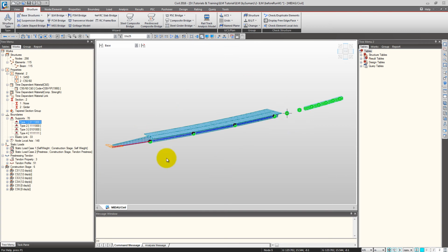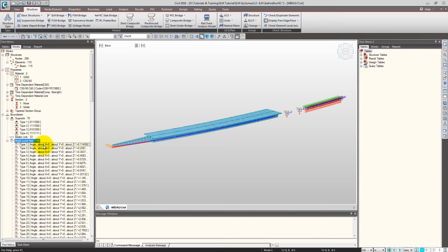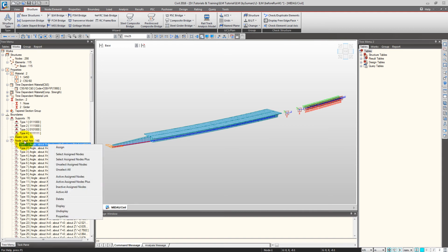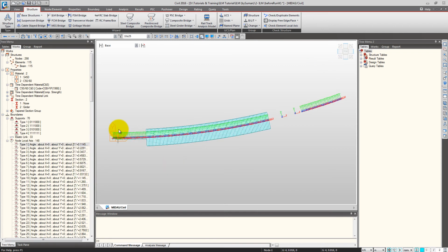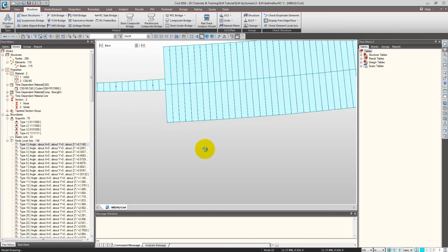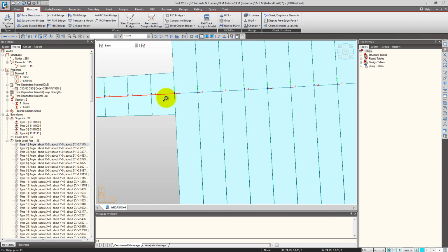So these are my final boundary conditions and the temporary boundary conditions, and the elastic links for the soil that we have defined in the wizard. As my bridge is curved, my support axis would be rotated with the node local axis feature. So in plan, if I show you, so you can zoom in. So the axis has been rotated. So my supports would be correctly defined.